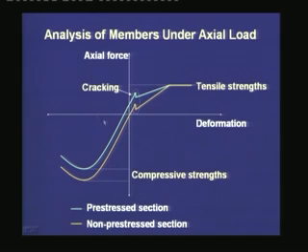On the other side, if you are applying compressive load, then we see that the behavior is similar to reinforced concrete, but it does not achieve the same compressive strength as that of the reinforced concrete, because here the concrete is under a pre-compression, and hence it reaches its ultimate strength at a lower external load. Now these two curves give the essential difference between a reinforced concrete and a prestressed concrete member. Now let us try to understand them with some logical statements.